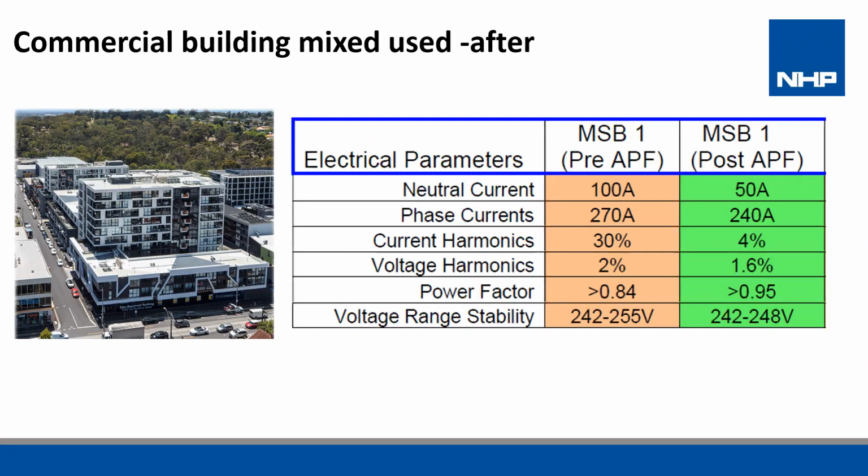So it is always advisable to conduct a power quality audit to thoroughly analyze the current, voltage, power, and harmonic distortion to ensure the right technologies are being implemented and get the most effective results on a site.